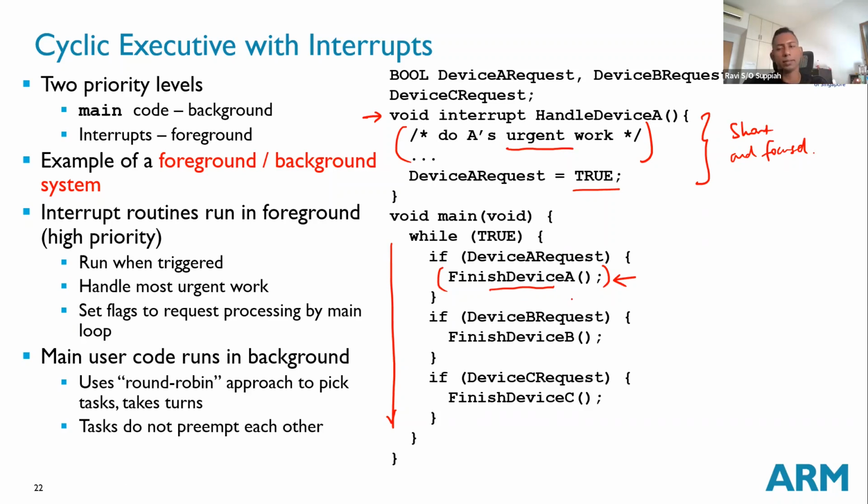Again, you can always change the behavior if you want, because in software you always have the flexibility to disable interrupts and enable interrupts again. For example, if I really want to make sure this is RTC, I can disable interrupts in the beginning, and after I finish I enable interrupts. So in a way this can help to ensure it runs to completion. But again, these are just tweaks you can make, depending on the behavior you want.